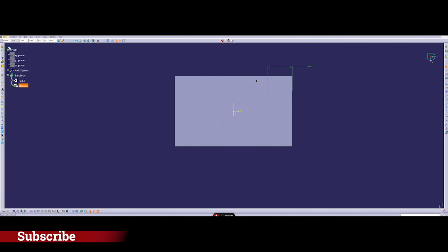And the second one is this one, which is 13 millimeters. Why do we do that? Because as I said before, in a two-dimensional design sketch, we have to constrain everything, because otherwise we don't know exactly how this will change in the future. So here, for example, we want this to be 15 millimeters, and also this one to be 15 millimeters.